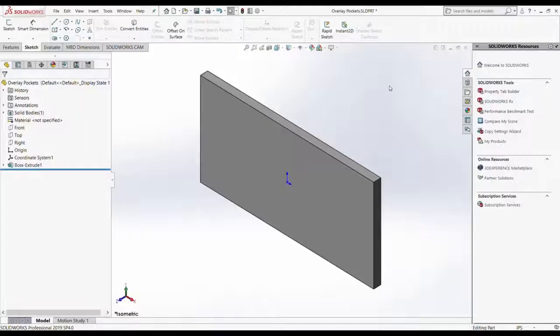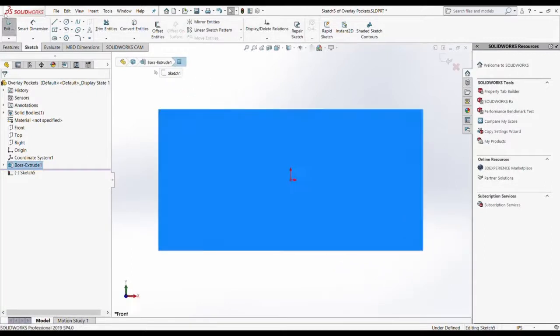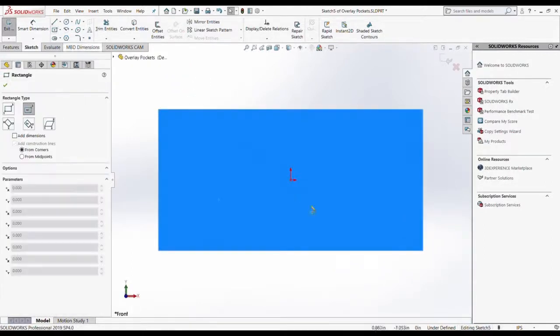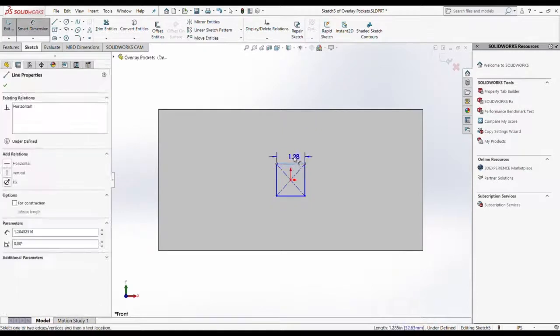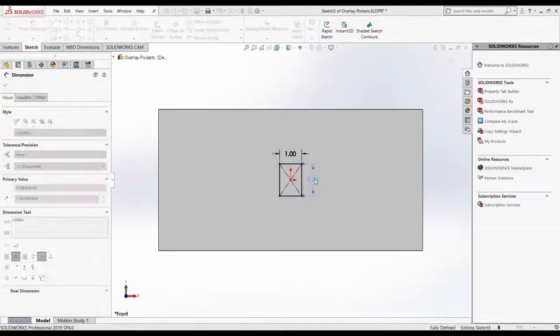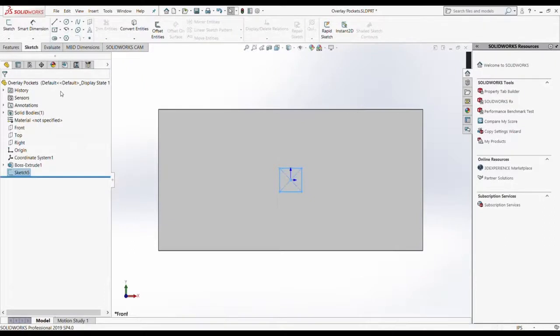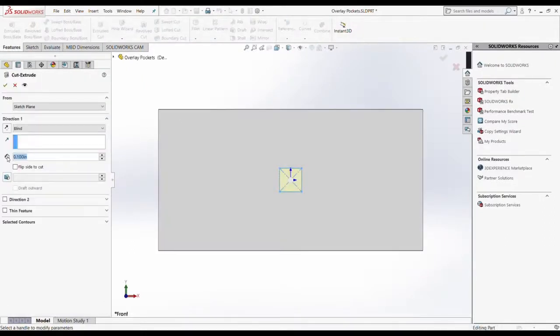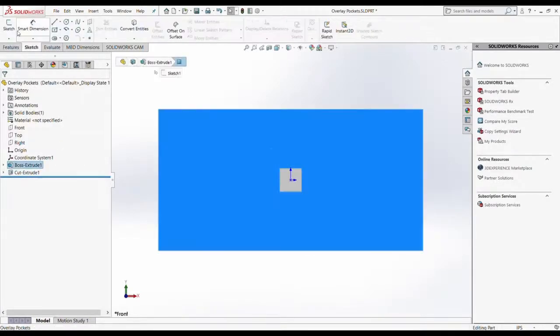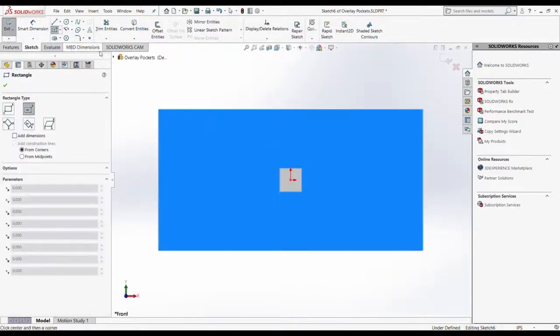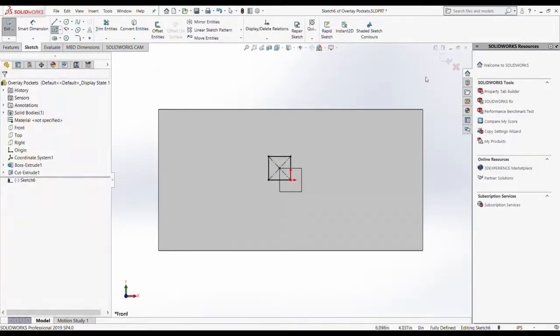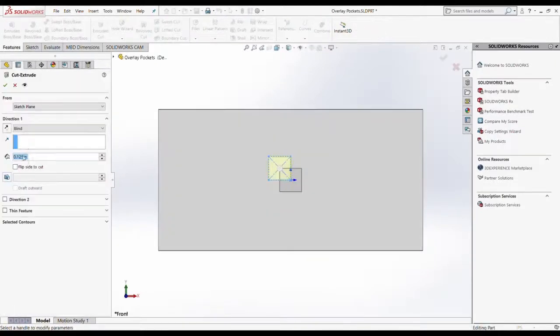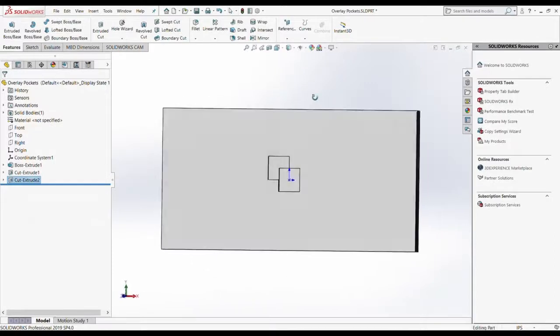Now, the first big step in the process is making a solid model. We mostly use Solidworks at Root3 for our solid modeling, and for this video I decided to just work up something quick that would highlight the 3D milling capabilities of the router. So I grabbed a piece of plywood, modeled that, and then you'll see me add in some layered pockets at different depths. As always, when designing a part, you need to think about how it's going to be made, so then you'll see me add in some fillets with a radius just a little bit bigger than that of the router bit I planned to use to round out the corners.